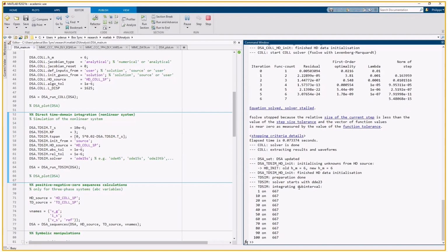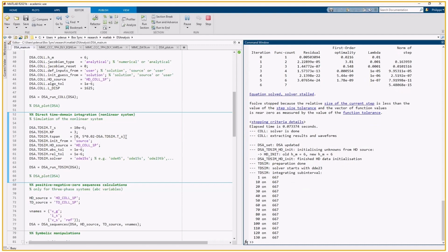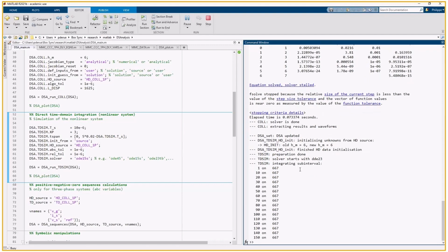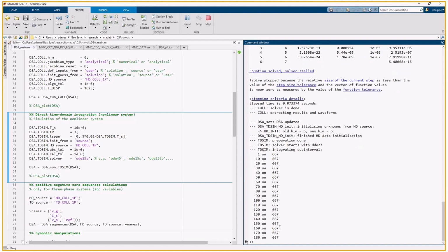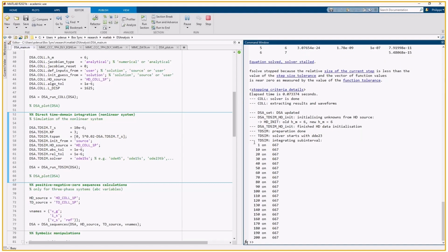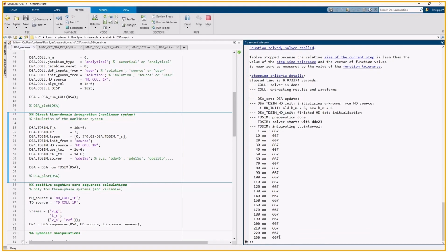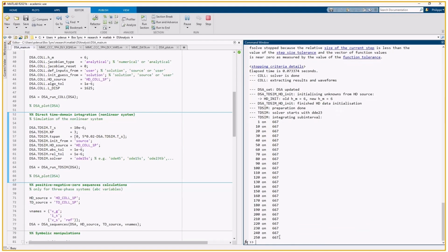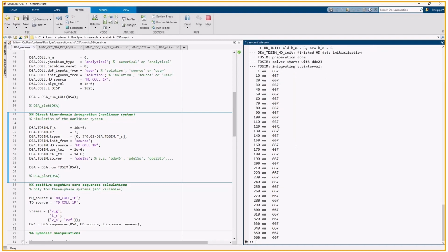For delayed systems, the complete time span is split into subintervals. Actually, each subinterval has the length equal to the smallest delay. And also you see that it is taking much longer. So it is much more computationally intensive to solve for a delayed system with Matlab. Please be aware that there are other ways of solving delayed differential equations. This is only one particular option.